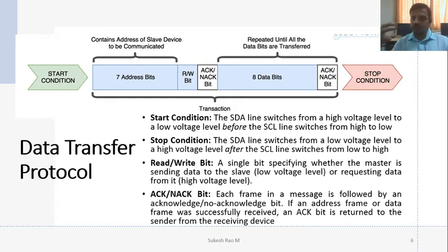So whenever there is a chip that has an I2C protocol, you simply have to write the register, and when you write some configuration bits, the communication starts by itself by generating the start and stop condition. So in MSP430 or the ARM, these are already implemented. But what we are trying to understand is the communication protocol, how this communication protocol is organized in I2C.